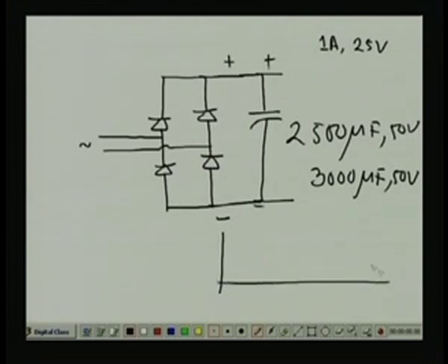My output voltage, suppose this is the output voltage, right, the output voltage will look like a slight fall, then again it will rise like this one, slight fall, because before the capacitor fully charges, again it will fall like this one. The output voltage, with the charging and discharging of the capacitor, will look like this one, almost steady DC voltage.